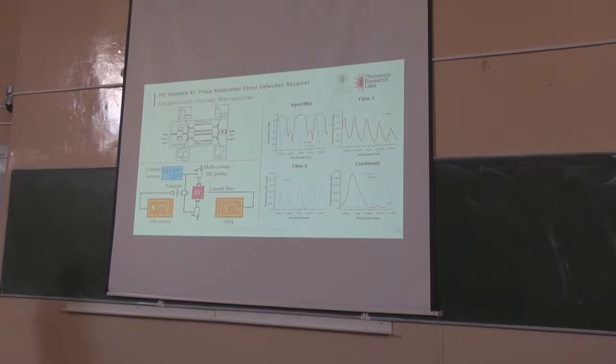Of course, you can see it is not exactly as we designed it. There are imperfections. As I have mentioned before, when you do these filters, even if you tune them very well, you get imperfections. One advice for you, if you are using photonic integrated circuits with thermal tuners, try to put them one apart from the other. Sometimes it's not easy because you need very high integration density. But then there is thermal crosstalk. Okay, so you try to tune this ring, but you're also tuning this one with this same tuner. Okay, so you need to compensate and to iterate until you find something similar to what you designed.